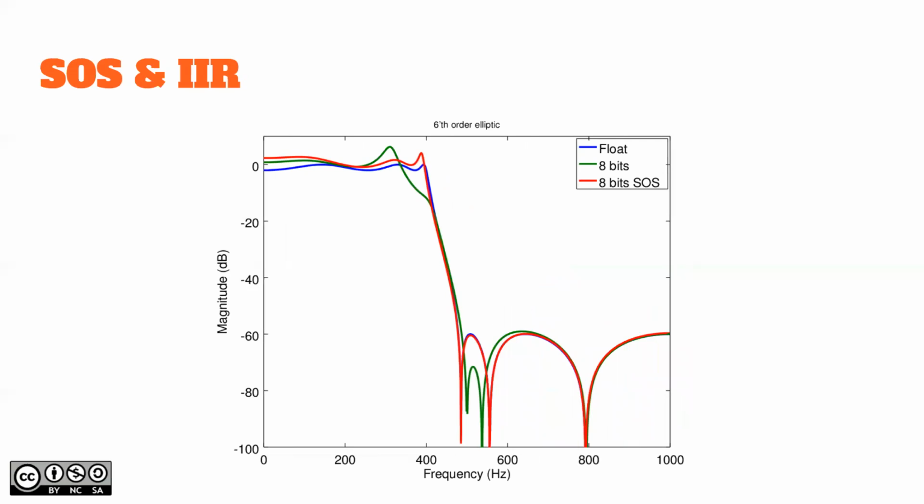With IIR systems, the problem is that you are moving the location of poles, which means that they can even go to the wrong side of the unit circle, meaning a useless, unstable system.